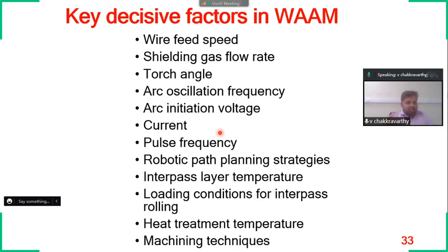We have to plan this pulse frequency based on the material. If it is titanium, more oxide layer removal should take place and less metal can be deposited, because titanium can easily get oxidized. For such materials we have to alter the polarity frequently, but for normal materials like stainless steel or inconel, we do not need to alter the pulse frequency to a great extent.